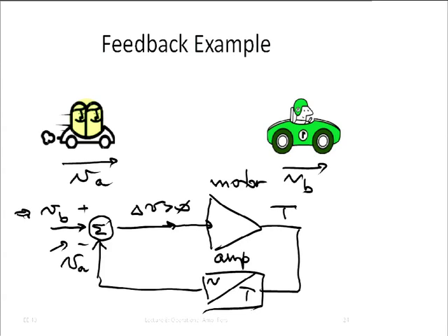Notice also this speed here, the difference between the two speeds. What is it? 0. It should be 0, right? That's exactly that voltage Vx, how we call it in operational amplifiers, right? That voltage should be very small. Well, here it's obvious, right? We want the two speeds to be identical. And there is even one other thing.